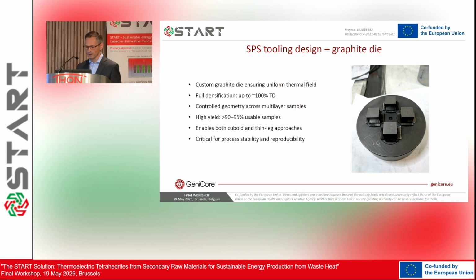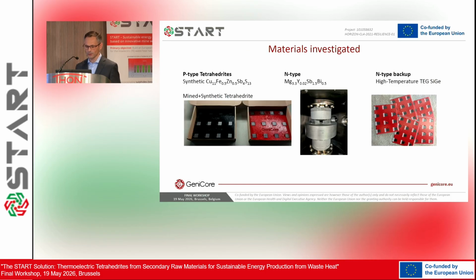At this stage, when we are moving to a multi-level system, it's important to use exactly the same thickness of the green pellets, because the pressing stamps must withstand the force which we use. You can imagine that if only one leg is higher, probably at the applying of the load, the system will be destroyed because of too high a load relative to the compressive strength.